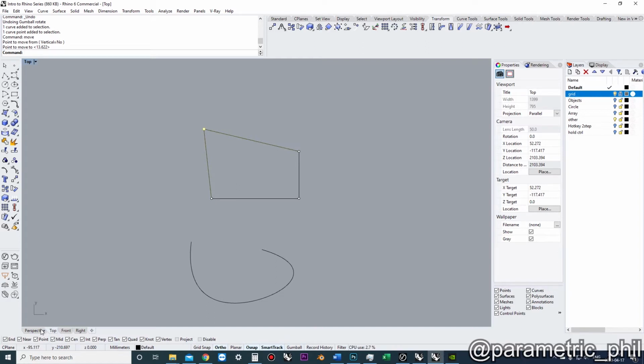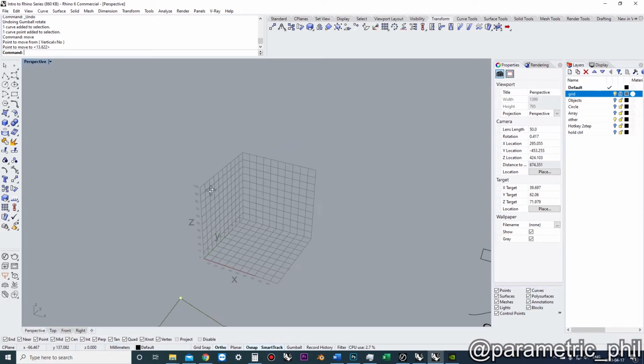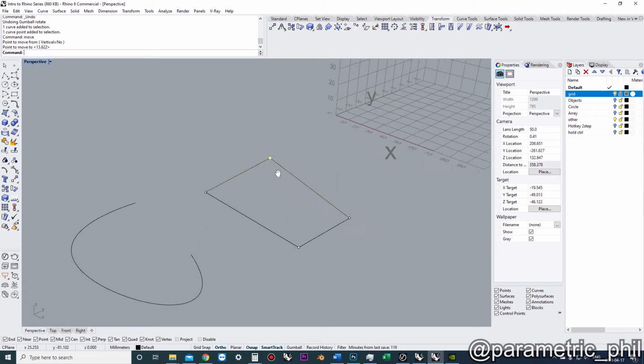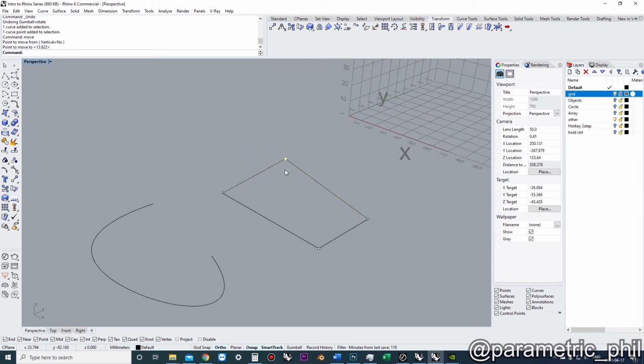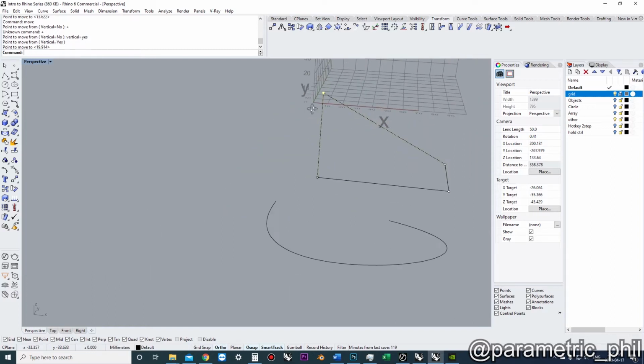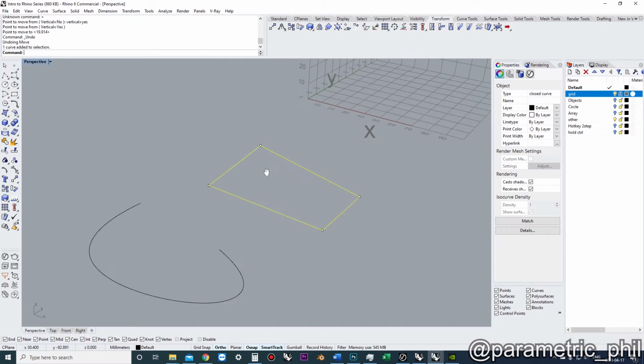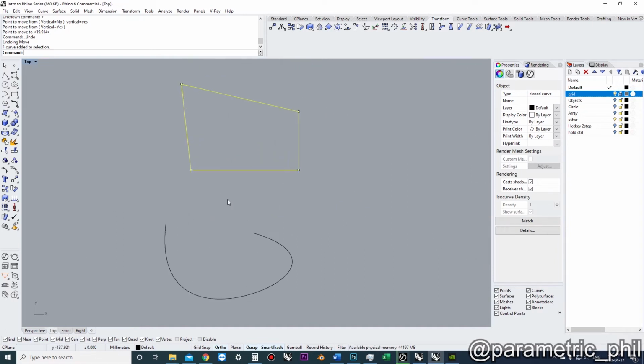On that note, I'm going to have a different video on hotkeys that will go more into this, but I have another hotkey so that when I press a similar hotkey, it will pull up move point, and then it will add vertical equals yes. So now I only move in the vertical axis. I like using hotkeys because I find it to be the most efficient modeling process.